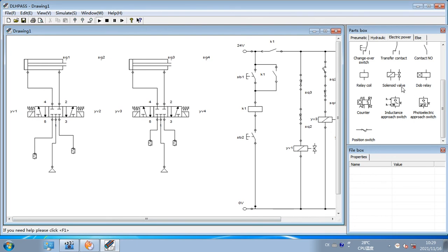Next, I want to do is to test this to see if it's properly connected. Press the button. It's not coming up, so next I want to do is to check what's going on. So you can check this key right here. This SB2 button right here is open, so there is no current flowing through. So you change this to a normal close. And then also you can see when you press this, it operates.